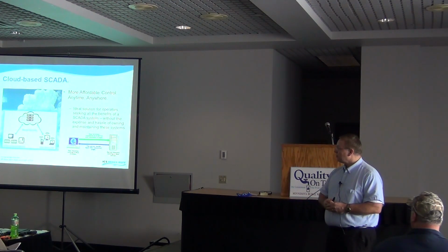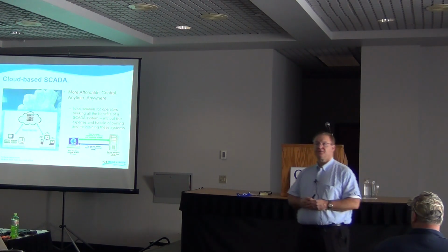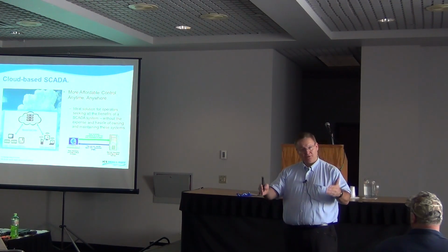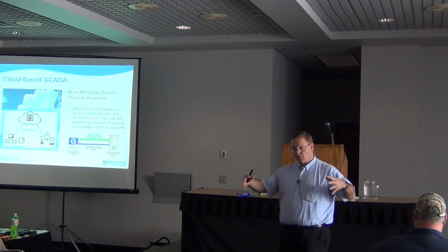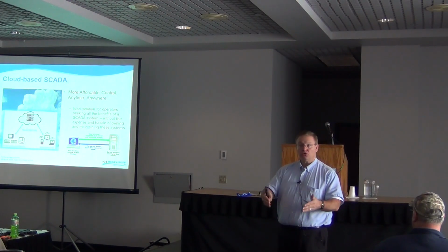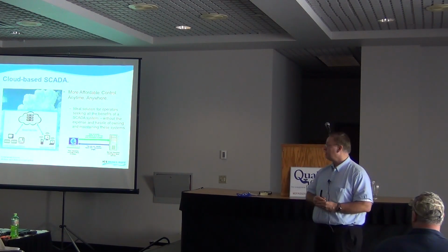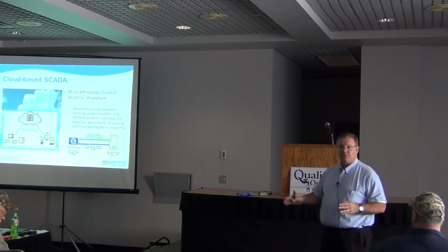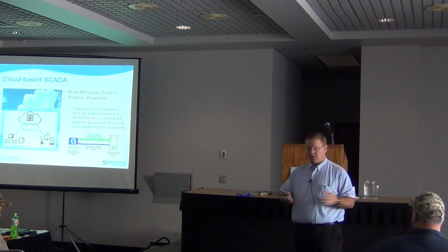One of the things that we're promoting right now, it's kind of evolving, is cloud-based SCADA. You've heard of cloud-based information. Basically, you're going out on the network, you're finding a server somewhere, there may be some application software there, where all of that resides on a server that you don't own, that you don't maintain, that you really didn't pay for. You're getting kind of free stuff out of it. With cloud-based SCADA, you don't have to buy the hardware, you don't have to buy the software, you don't have to maintain the system. So that can take a lot of cost out of these systems, a lot of worries, and a lot of complexity.